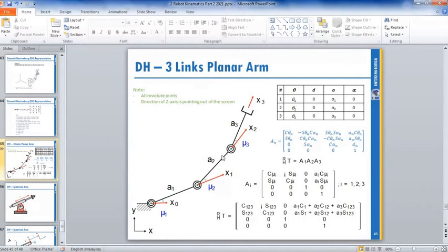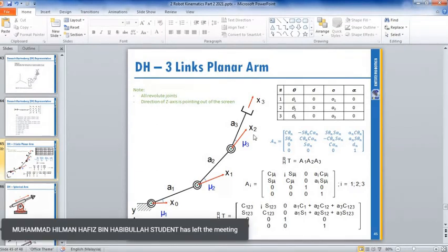If you change your length, maybe you can change here, or maybe you need to recalculate back. For me, I think you need to recalculate back because these values are mixed up. After you multiply into a matrix, this value is already mixed up. So if you change your robotic arm length, you need to recalculate back your matrix because this matrix is specific for this robotic arm.